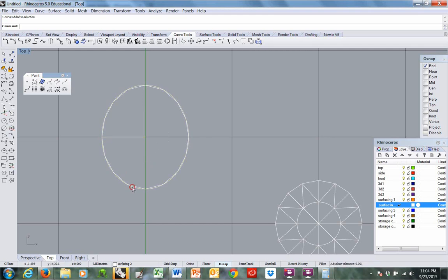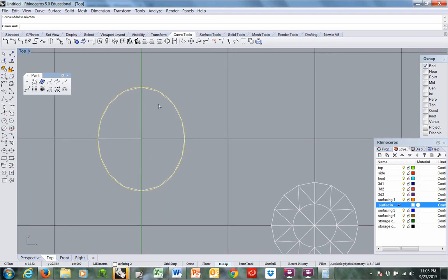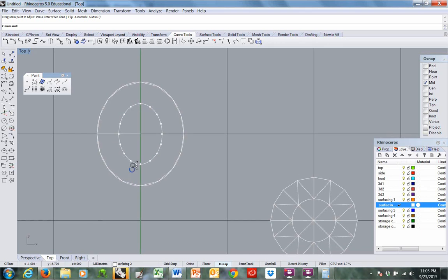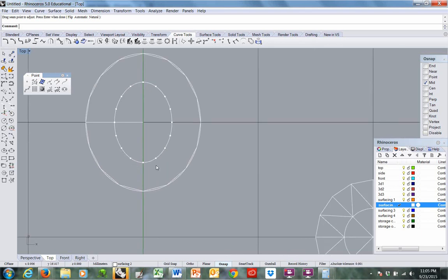Okay. I'm going to need to pull this in, offset the circle, the ellipse, instead of that polyline. See if I can't get a better drawing. Through point option, mid. Divide my curve by 16. I don't need to draw a polyline. All I really needed were the points.